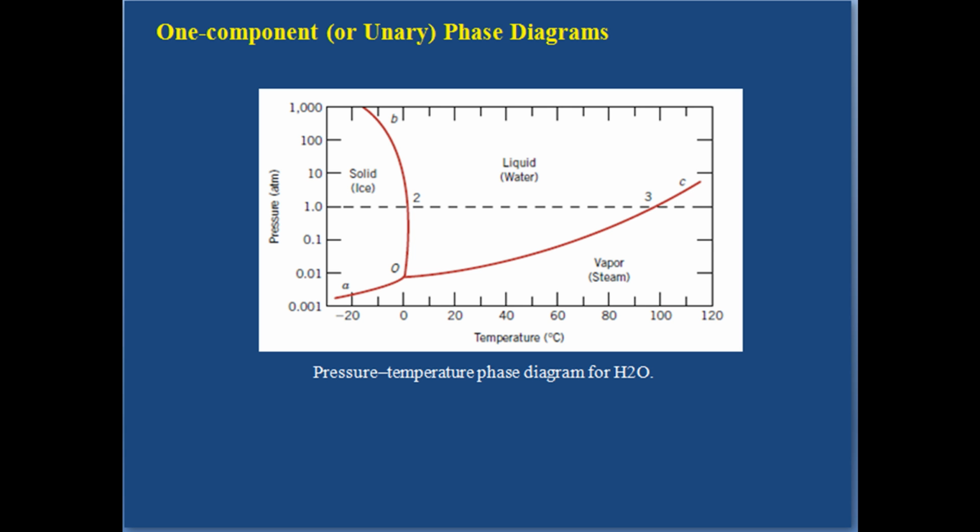Much of the information about the control of the phase structure of a particular system is conveniently and concisely displayed in what is called a phase diagram, also often termed an equilibrium diagram. Three externally controllable parameters that affect phase structure are temperature, pressure, and composition, and phase diagrams are constructed when various combinations of these parameters are plotted against one another.